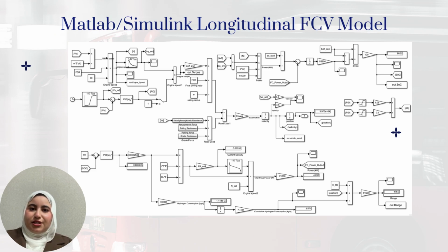Road load calculation and tractive force are the same as for the EV, with the same 95% depleting efficiency and 90% regenerative efficiency used. As the fuel cell vehicle has a small battery, state of charge of the battery is calculated in a similar way to the electric vehicle model. State of charge of the battery is initially set as 80% throughout the cycle. Using a PID controller, we try to keep the state of charge constant at 80%.